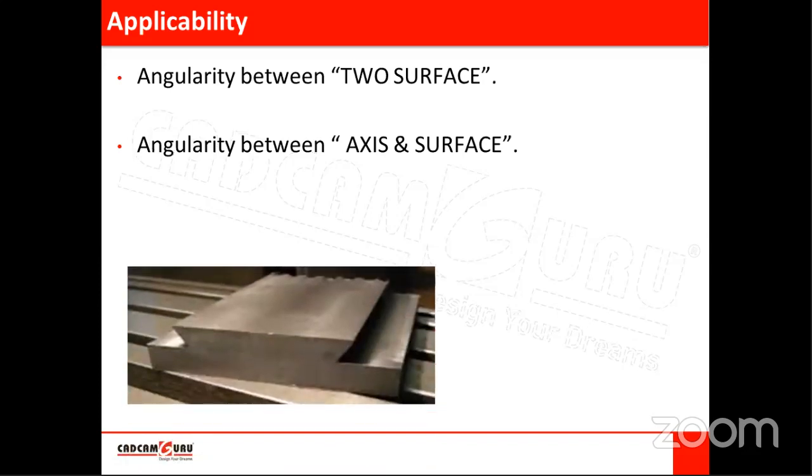So this is a dovetail guide. So this is used for guides or slideways of different machines. So you will find these slideways if you see the milling table of a milling machine or the table of some different machines. Okay, so the machine bed will slide along these slots or the guides.